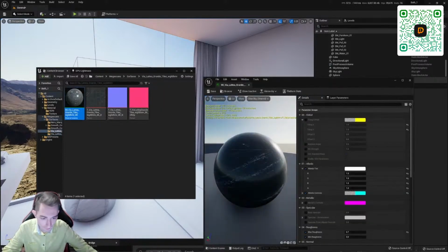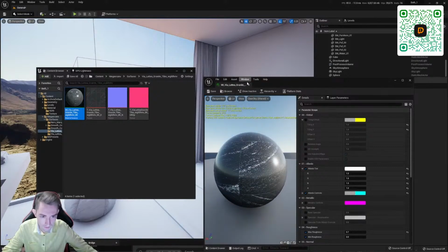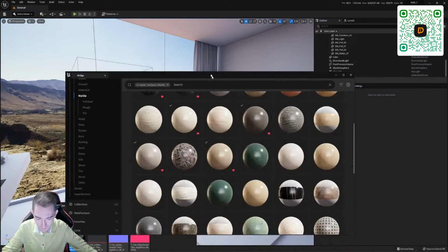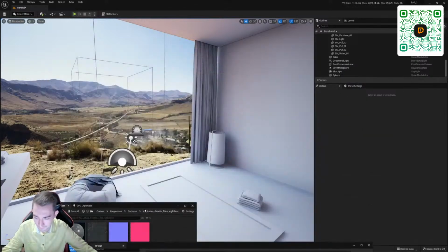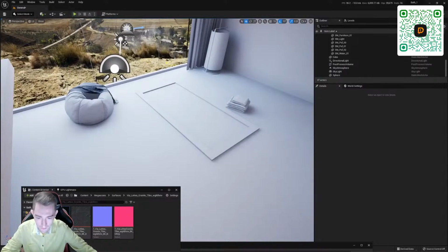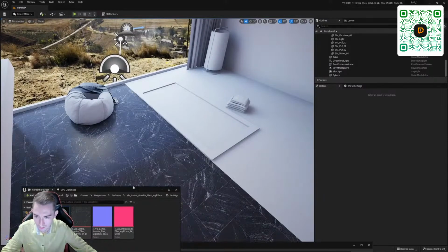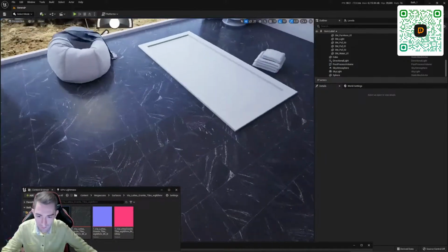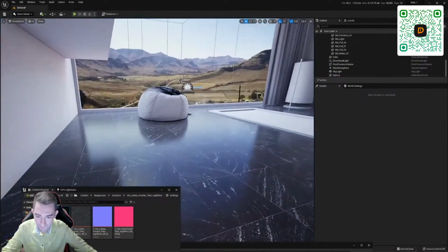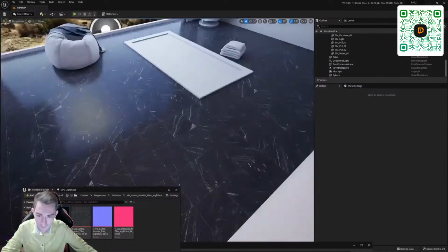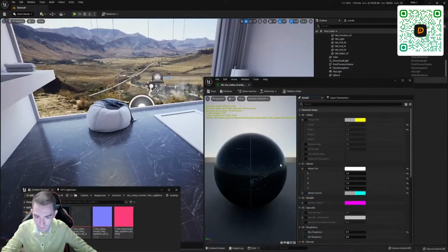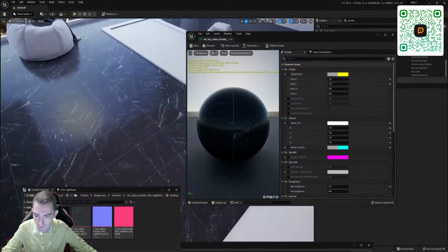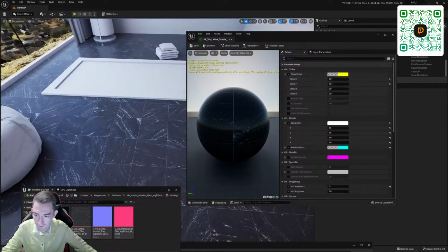So, I have this material here, the tile material. It seemed to me the most suitable. It is downloaded from Quixel Bridge. We just transfer it like this to the object. And this is how it looks here. Here you can configure it. I click on the material twice. Tiling. Tiling suits me, although you can even change it a little.